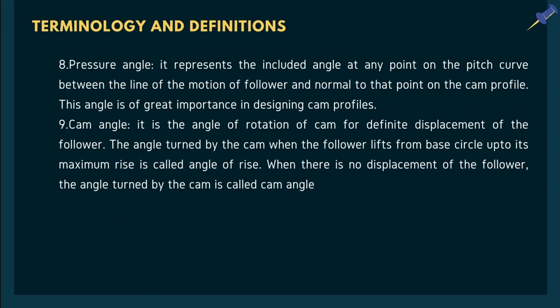Next one is pressure angle. What is pressure angle? It represents the included angle at any point on the pitch curve between the line of motion of the follower and the normal to that point on the cam profile. This angle is of great importance in designing cam profiles.